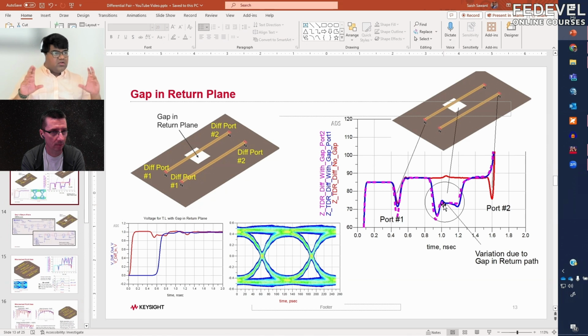So it's also not a great difference like the way we saw it in the previous example, right, where it had meanders. From 80 it went all the way up to 120 plus. So that was a very large difference. This wasn't that large of an impedance difference. That's why you don't see much reflections. So what is that ballpark region, or why you are seeing this, will help you build intuition and understanding as you go forward basically.